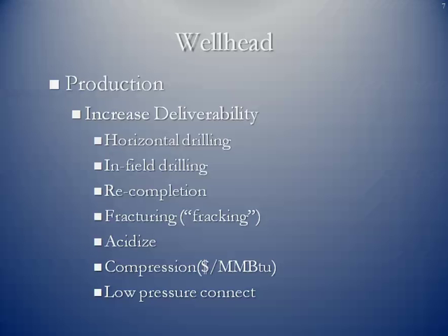Of course, fracking is a form of initial releasing of the production. It can also be done multiple times if you think that there's more to be released. Acid is one of the ways in which wells are completed. It's an older method than fracturing, but if you have a well that's in decline, then you may agree as a producer and an operator together to go ahead and try and use some acid to free it up. This works mainly in places like sand formations.